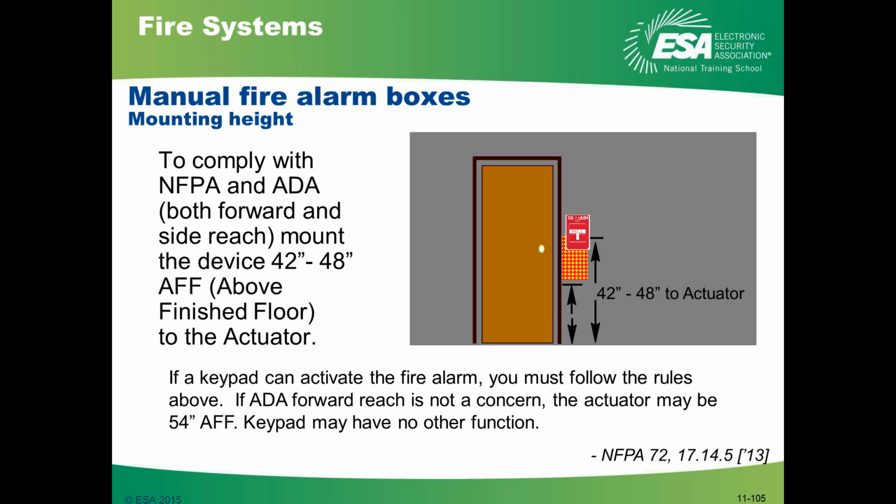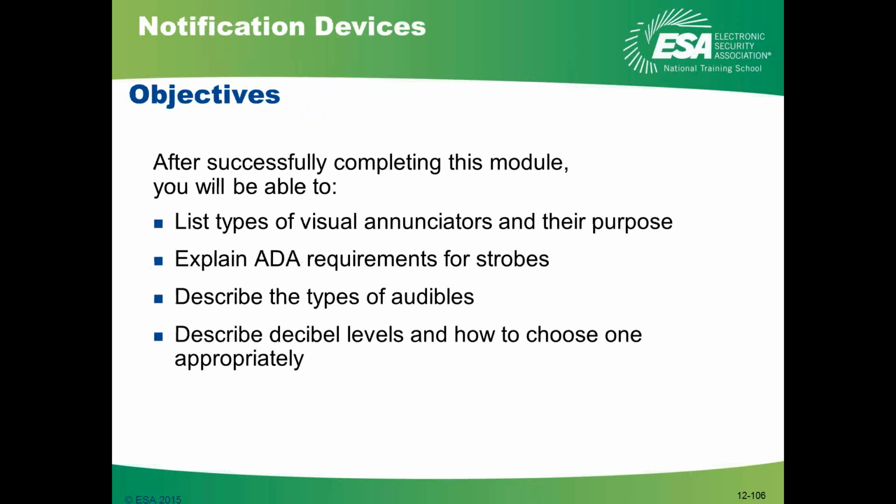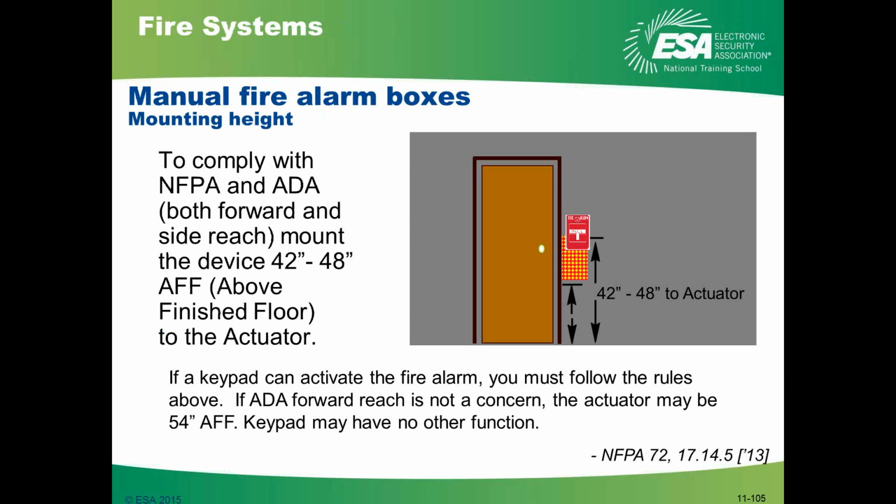And then we have the normal mounting height for the fire alarm box, which is a pull station. You'll also now find in 72 that the term pull station was actually added in a parenthesis. They finally acknowledged that in the field we don't call these things fire alarm boxes, we call them pull stations. Any further questions on fire systems?